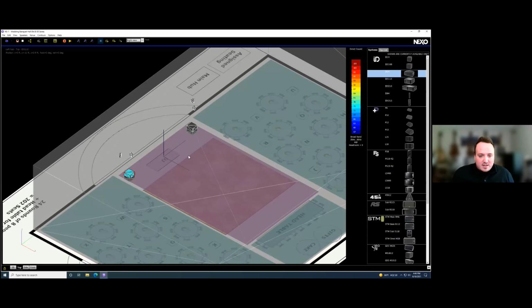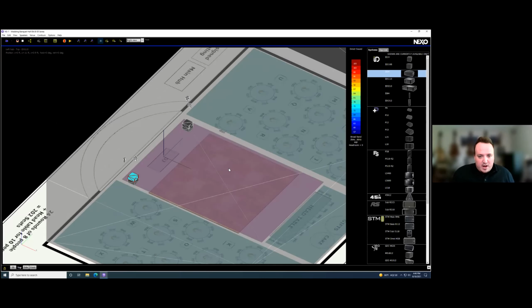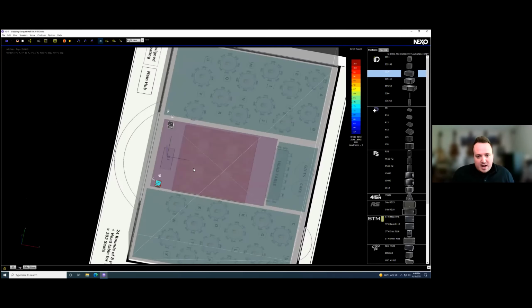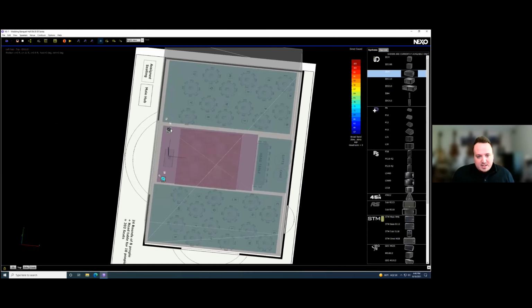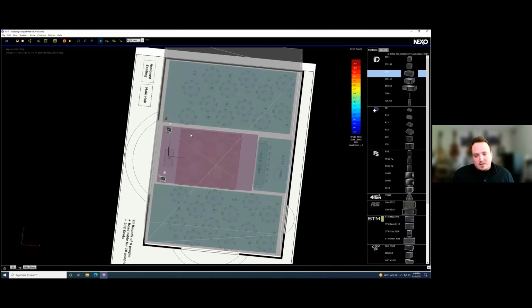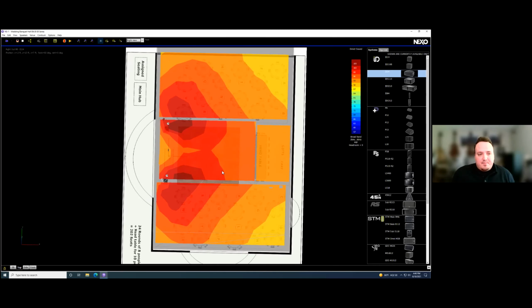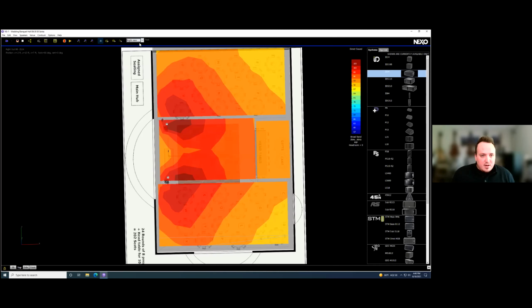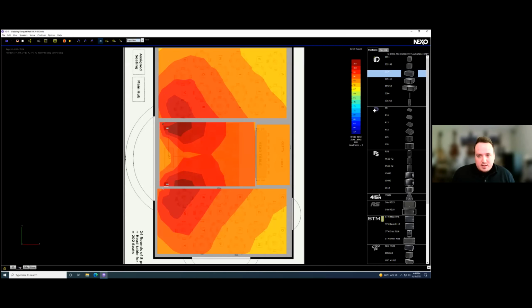So, obviously looking at this scenario, the ID24, when it's pole mounted on top of a sub, or even just freestand pole mounting over here as a fill speaker, it's not going to throw like a line array, because it's not a line array. But from a portable standpoint, what do we get when we turn something like this on? And you could see here, we're getting still some serious decibels out of there, 105 dB, 2K to 8K.